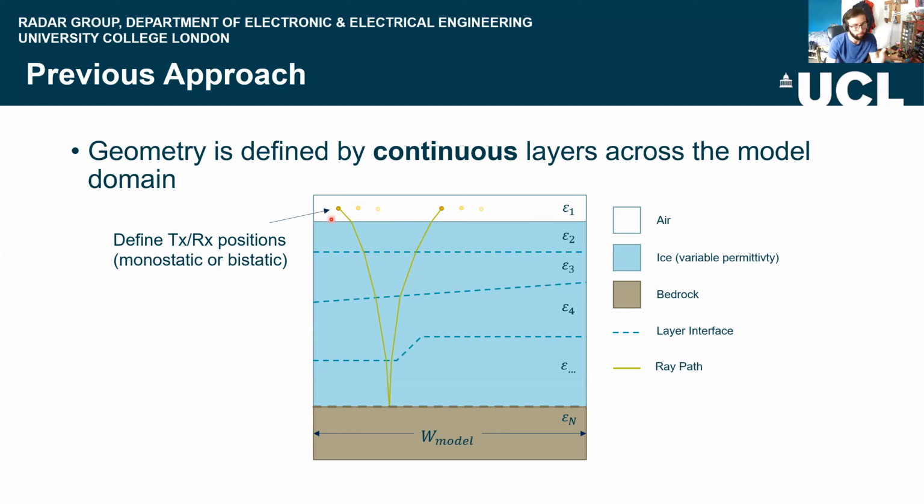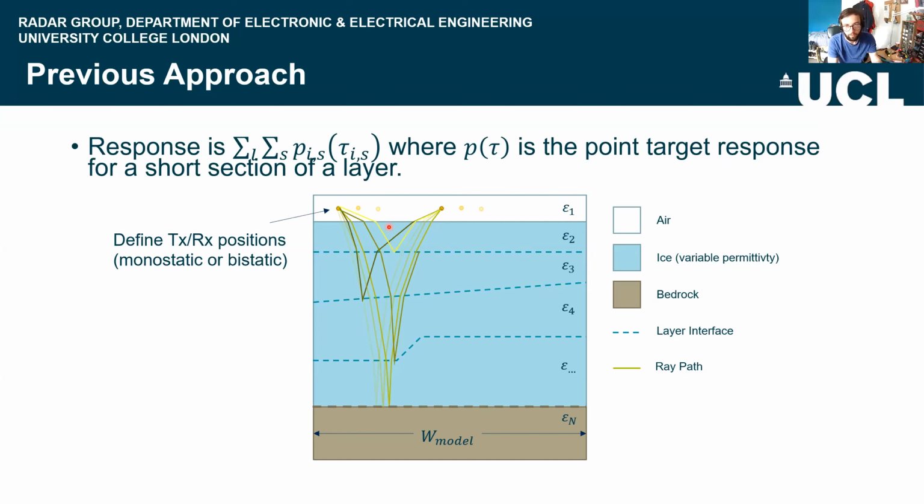And yeah, so then, like I've said, we also need to define the radar configurations. That's whether it's the transmit, receive positions, etc. So then to get the radar response, the first thing we want to be able to do is to get this in the time domain. This is the deramped FMCW response.